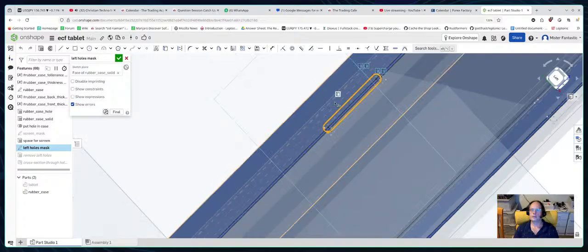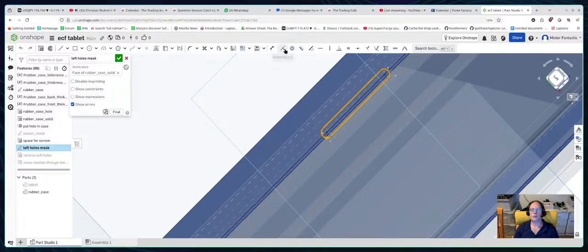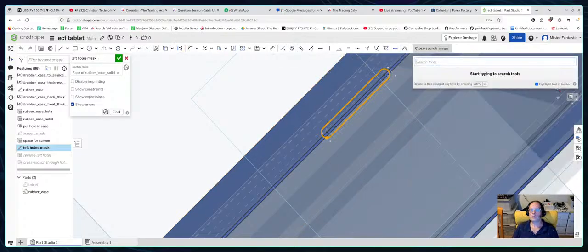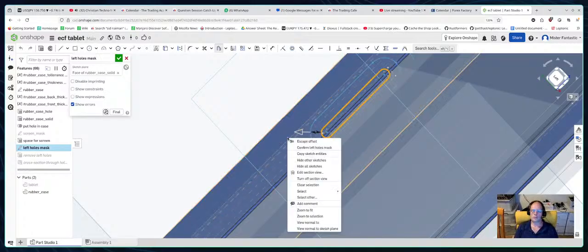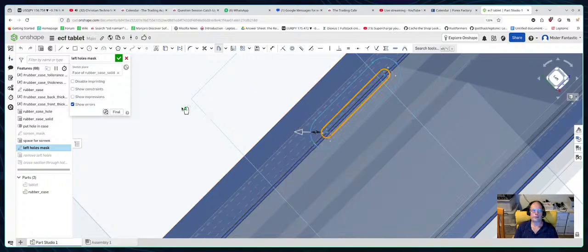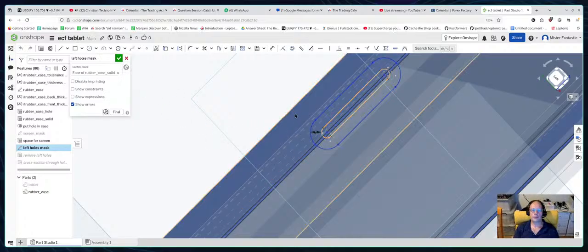That's everything pretty much. We're going to do outline. What's it called? I think it's this thing. Offset. Not 5 mil, maybe 2 mil. Yeah, and that'll make it bigger on the outside than it is on the inside. And save.